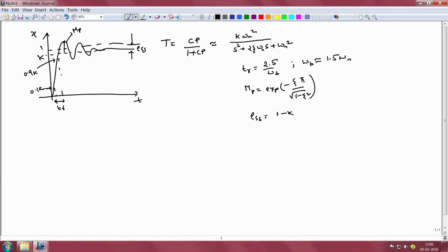So, we have to check both for closed loop specifications and for time domain response, because there are approximations that are made in going from time domain to frequency domain and from closed loop to open loop. We also discussed that in the interest of appealing to a broad audience, we cannot focus on any one kind of input that might be of interest to one specific community, and we have to decide on a particular standard input. So, we chose the step input as the reference input, and the response to a step input, namely the step response, would be the one that we would be looking at to evaluate the performance and stability of our closed loop system.